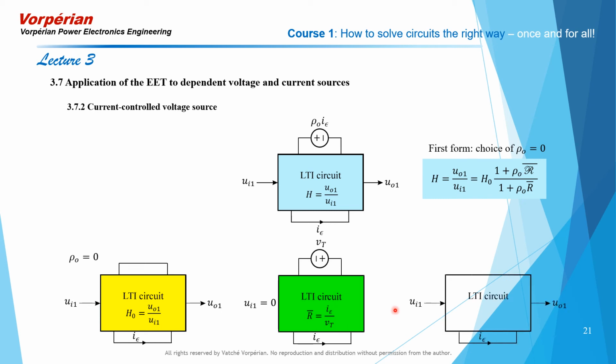And then finally, you compute the null inverse gain, where again you replace the dependent source with an independent voltage source as shown, pointing in the opposite direction, and you null the response and you determine the inverse gain, I epsilon over Vt under null response conditions. And that gives you your script R bar.